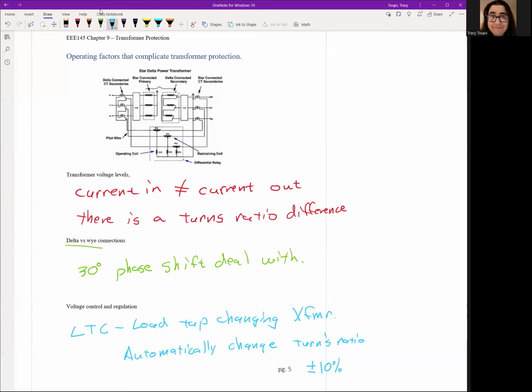We don't want the customers to wake up at night and have like 135 volts on their electrical output at their house, because you're going to burn up all their equipment. You also don't want the customers to be at like 5 o'clock in the afternoon, want to run their AC and the voltage dips down to like 90 volts, because then things will shut off. So LTC is there to make sure we don't get to those extremes and stay roughly within that 120 voltage range.